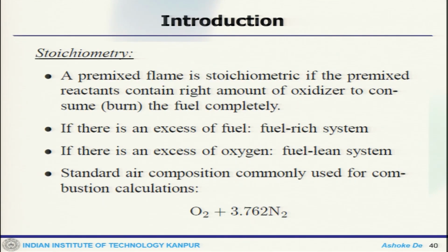Now, another definition when you talk about the premix flame is the stoichiometry. Typically the premix flame is stoichiometric if the flame reactant contains the right amount of oxidizer to consume the fuel completely. That means if I mix x amount of fuel with y amount of oxidizer, the proportion is rightly matched so that you get a stoichiometric situation.